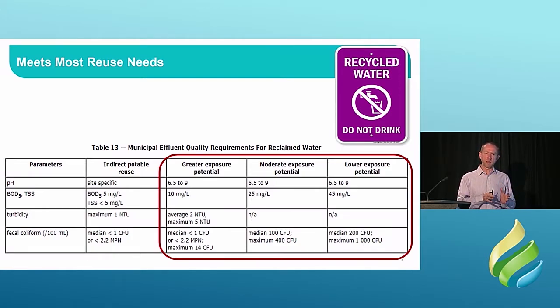With that kind of level of reuse, if you're looking to do that, then you're into membrane filters. But any of the other 3, which is the vast majority of reuse applications, things like irrigation, toilet flushing, spraying water in parks, whatever it might be, then a disc filter is going to get you there. I should say that there's also a coliform requirement in those standards, and a disc filter isn't a disinfection technology, so you will need to disinfect as well. But in terms of the need for filtration, the disc filter will get you to those 3 standards.